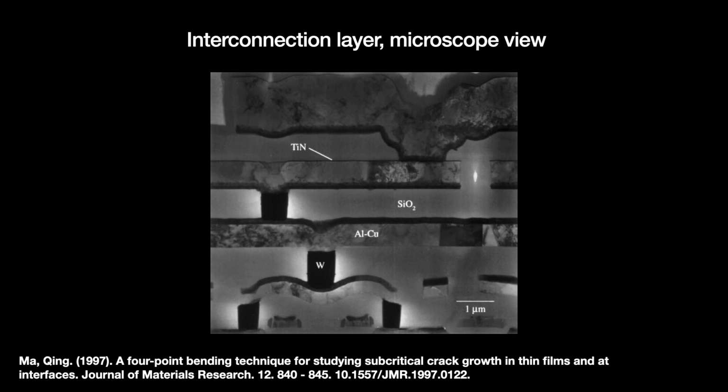Generally speaking, an IC has two types of interconnects, local and global. Local interconnects occupy the chip's lowest levels and connect local circuit blocks. The wires are very short, so designers are less concerned about line resistance than they are about other factors like heat. So I don't think a room temperature superconductor, which would be quite sensitive to heat, makes sense here at all. Global interconnects are higher up in the strata.